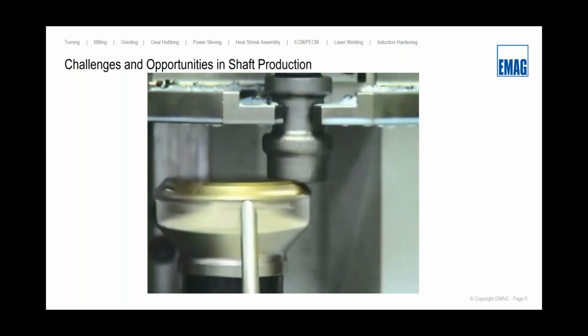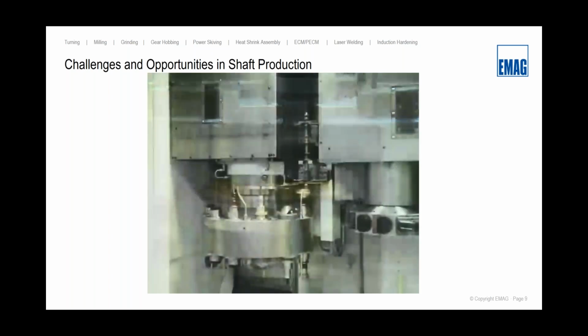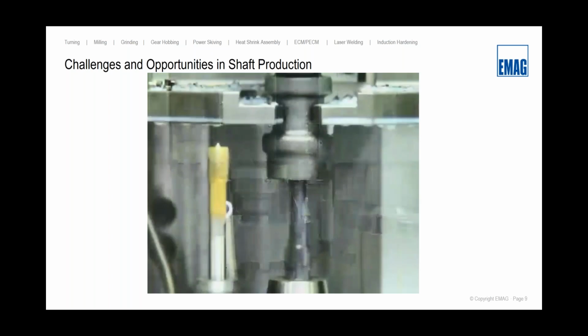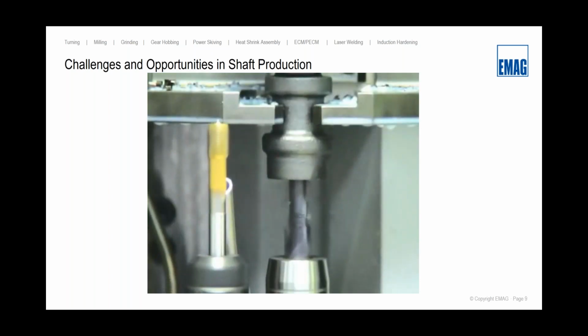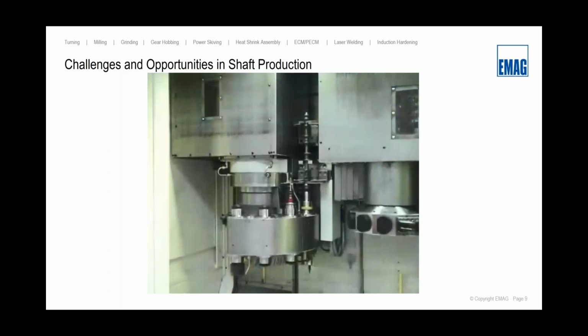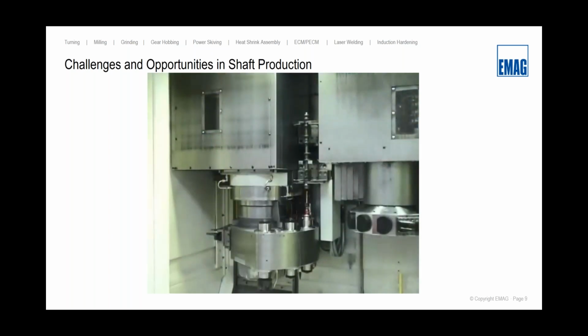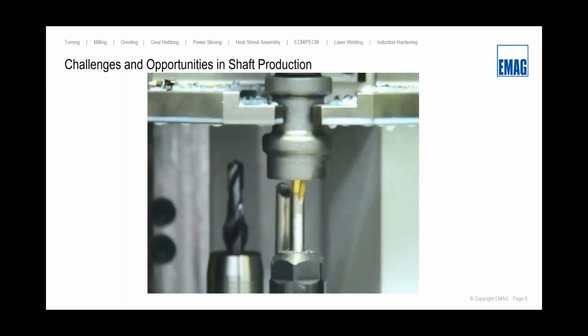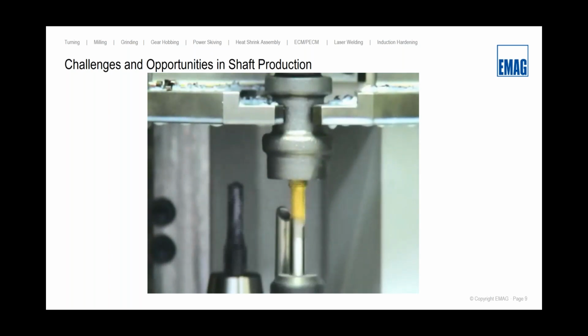So not only are you buying one machine to do the turning and the milling, you're also getting the automation for free. So you can see that we did the machining of the top half of this camshaft, we milled the face, we drilled it, and we also put a hollow mill in there, which is going to be my clamping diameter for my next station for the turning. And then I moved my fixture up and my elephant foot turret down, and I did the same operations plus the threading of the ID here.